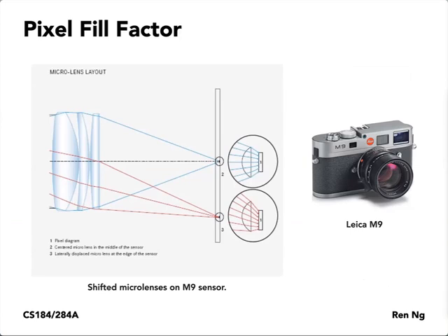So as one of the topics that comes up, for example, here's a schematic of a high-end camera. This is for a Leica M9, which is a pretty fancy high-end camera. Here's a schematic of the back portion of the lens and a drawing of some of the rays that converge to the sensor, which is a pretty large object relative to the back of the lens, right? It shows that if you're a pixel at the center of the sensor, then the rays of light that arrive to you are geometrically centered. And so you want to take this blue set of rays, which is symmetric, and put it through a microlens to arrive at the sensor surface, at the photodiode portion.